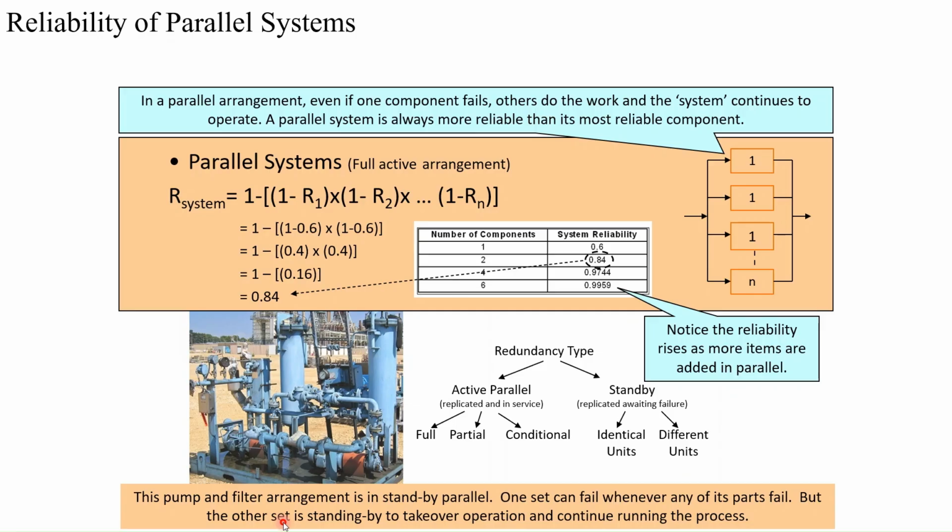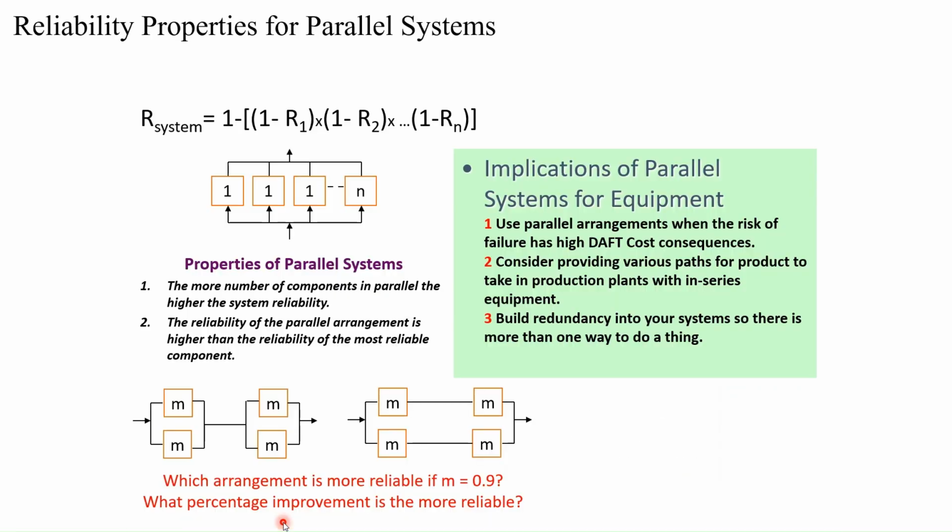Consider a server with 2 independent power supply units, PSU, each having a reliability of 0.95, 95%. The system is designed so that if one PSU fails, the other can still supply power. The system will fail only if both PSUs fail simultaneously, which is a rare occurrence. Mitigation strategies to further improve reliability: use more redundant components. Adding a third PSU would further improve reliability.